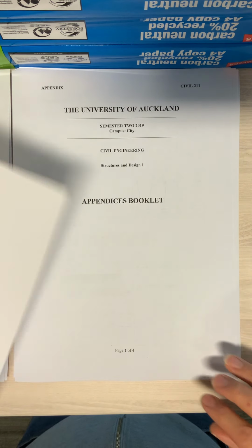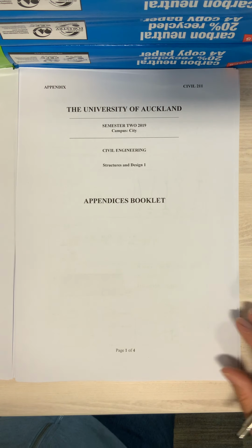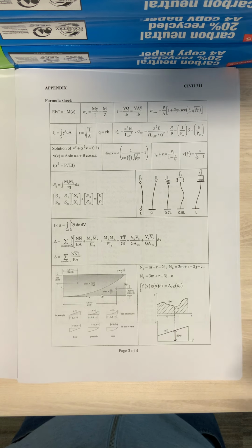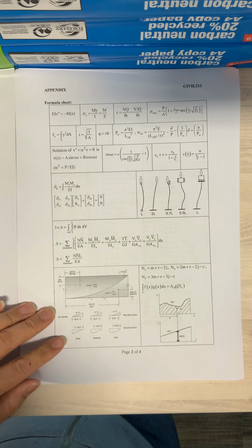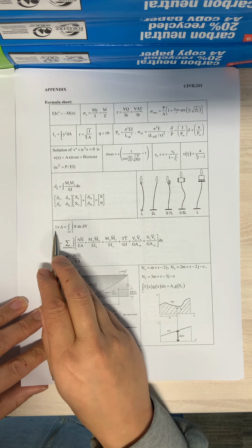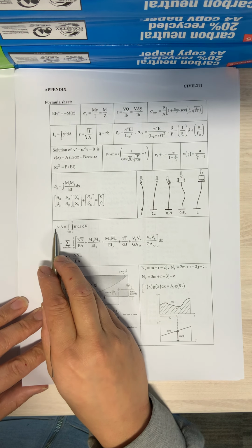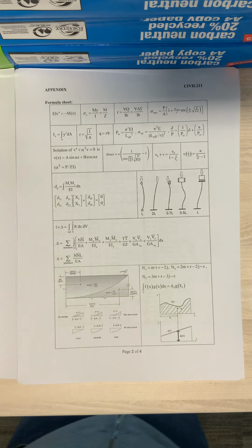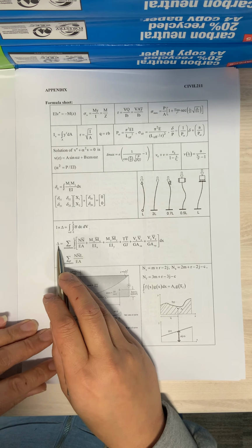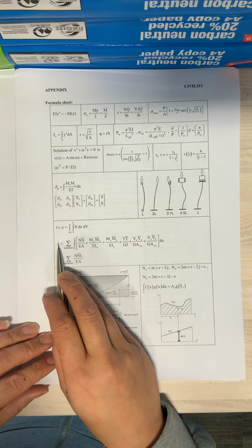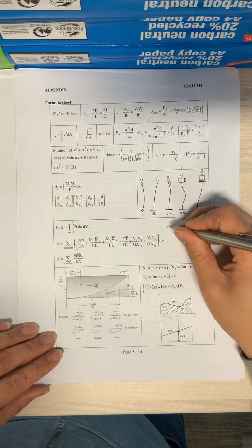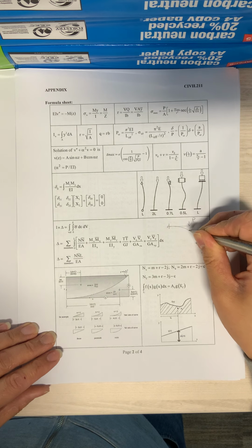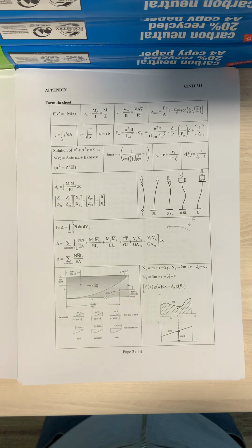Okay. Right, so now let's have a look at the appendices of the course. So this is what you will get in the exam. So you may or may not recognize that. That basically says the external virtual work is going to be equal to the internal virtual work. This would say, what is your deflection? So that example 3, or the cantilever. So you've got a cantilever under a load P, and that cantilever would deflect something like that.